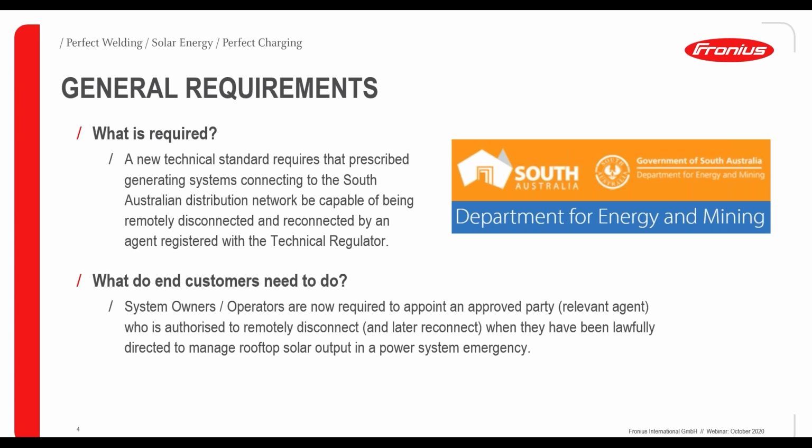Okay, so general requirements. What is actually required? Obviously the South Australian government have implemented this new technical standard, basically requiring generating systems to be able to be remotely disconnected and reconnected by an agent registered with the technical regulator.